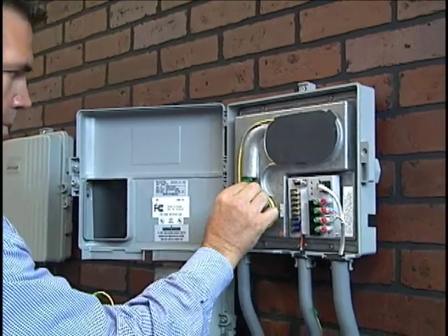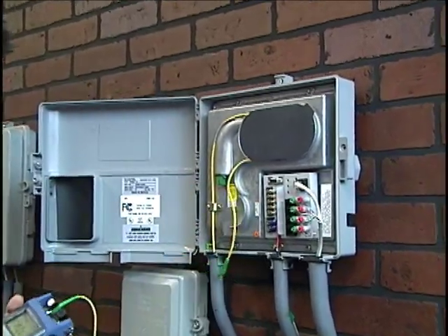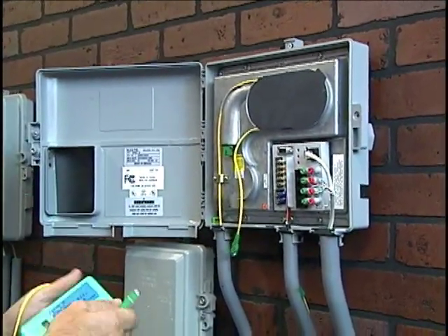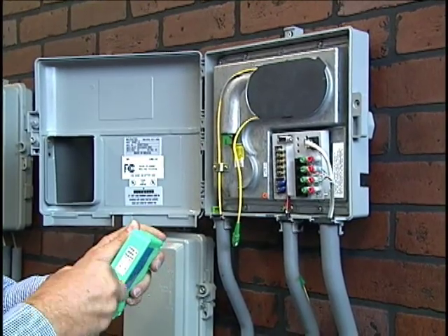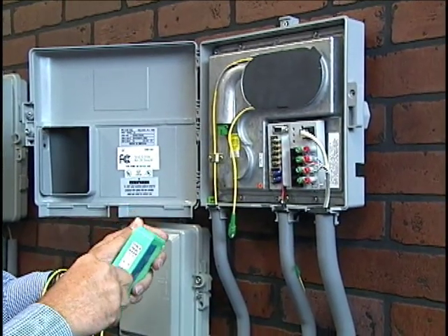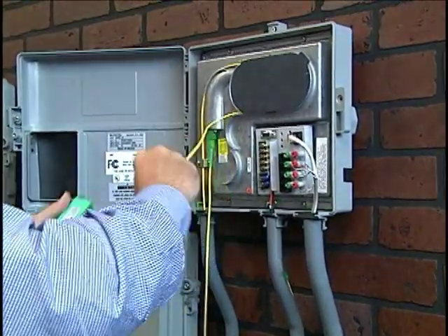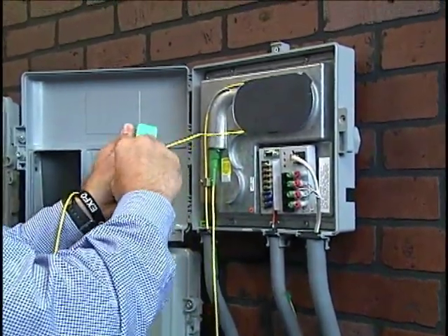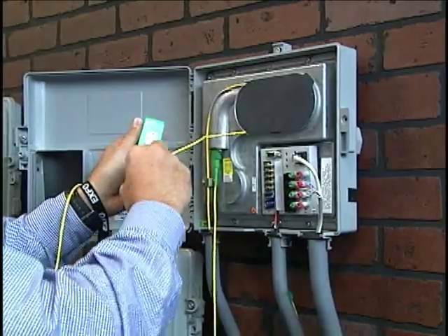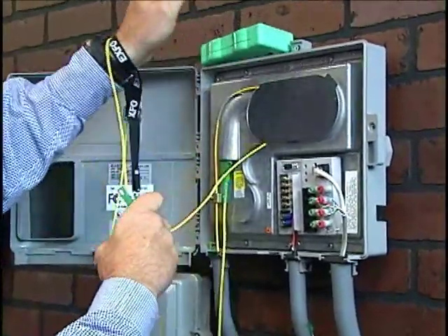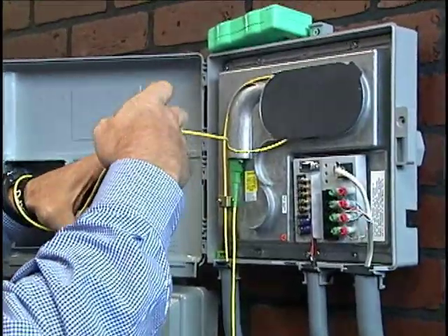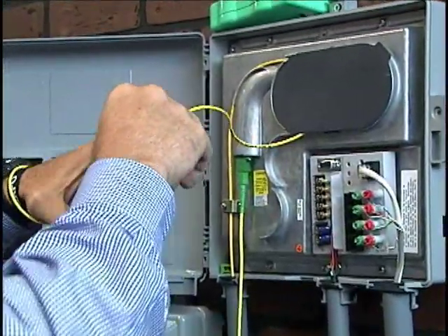The ITU standard specified the optical wavelengths, attenuation, reflection, and dispersion values required using the ITU standardized G.652 single-mode fiber. By using standardized products originally developed for DWDM, the PON network design reduces the installation and operating costs by eliminating active components between the transmitting terminal and the subscriber.